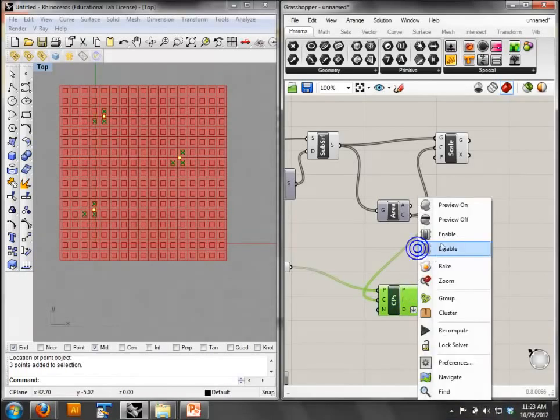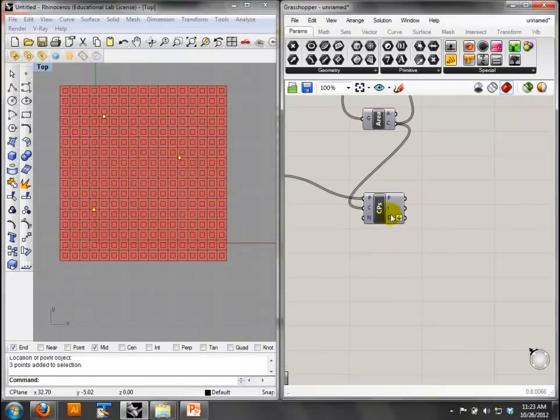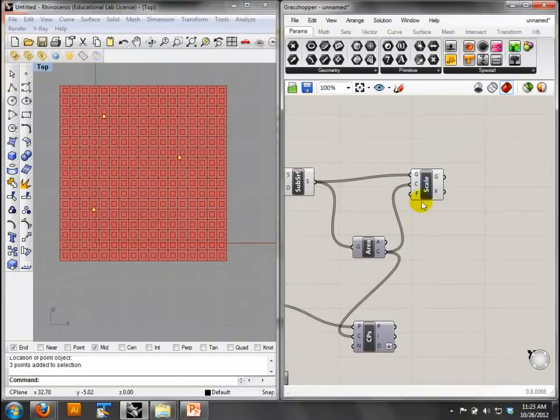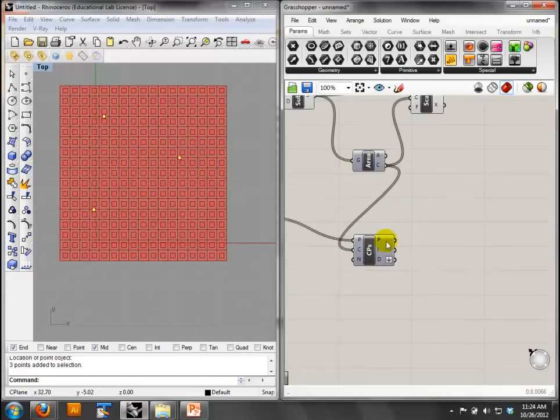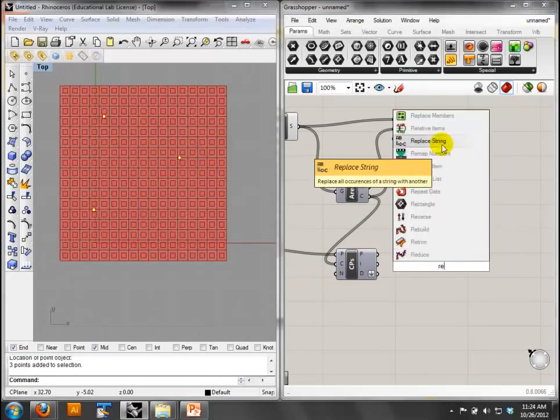Okay, I'm going to go ahead and hide this here. Okay, the other thing that we're going to do though, so we get a list of values, and there's a pretty wide range in there. Remember that scale takes a scaling factor, and it's some number, so it's basically like multiplying that. So 0.5 is 50%, 2 would be twice the size, right? So we can't just feed raw distances into this thing and expect to get any kind of meaningful output with that, all right? So I'm going to show you another trick. So we talked about closest points. That's a new one. The other one I'm going to talk about is called remapping.